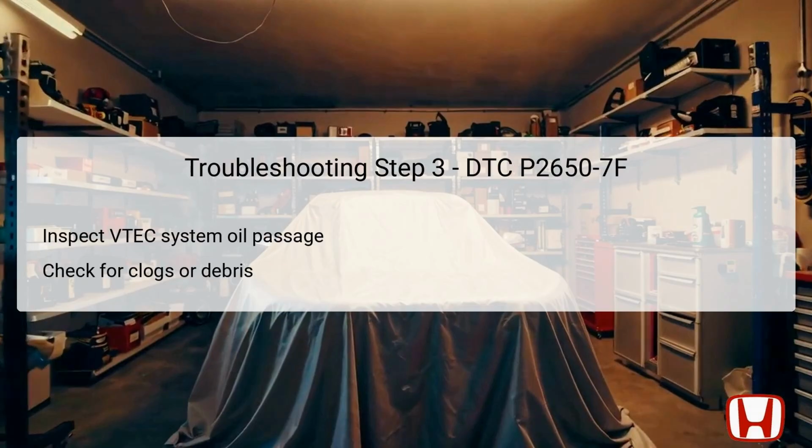The third troubleshooting step involves an inspection of the VTEC system oil passage to ensure there are no clogs or debris that could hinder oil flow. Blocked oil passages can significantly restrict the flow of oil necessary for activating the rocker arms properly. To carry out this inspection, you will examine the condition of the oil passages visually and may use a cleaning tool to dislodge any debris found inside. If there is any blockage, clearing the passage can resolve the pressure issue.